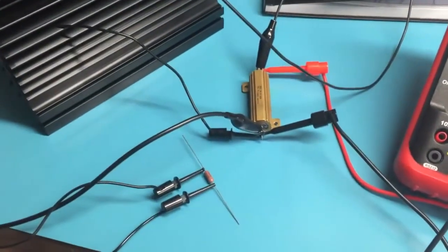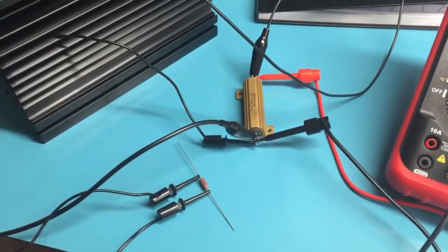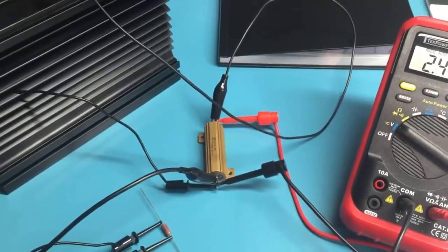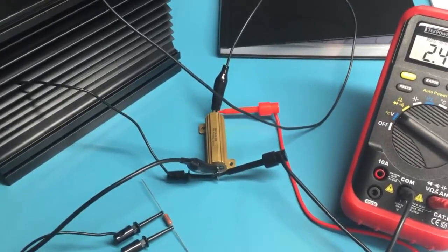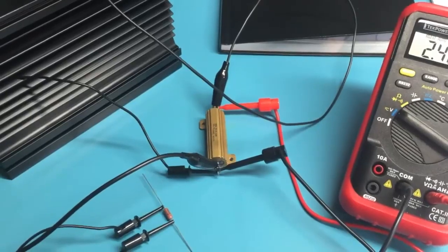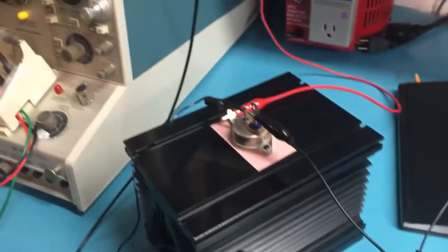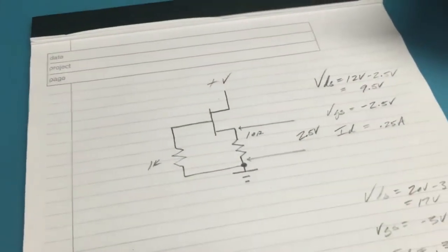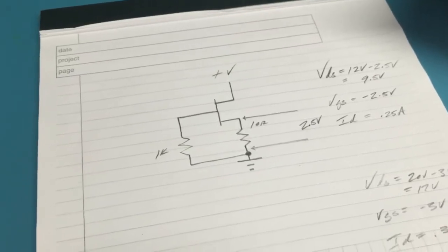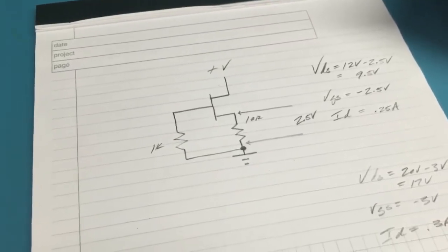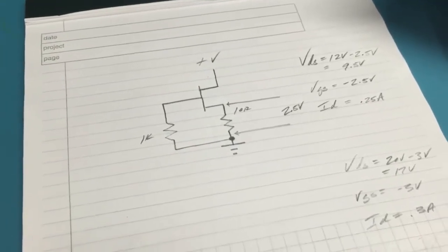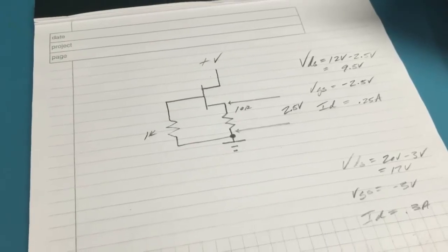You can see we've got a 1 k ohm quarter watt resistor there, and a 10 ohm 50 watt power resistor. It's not on a heatsink right now, so it's derated to 5 or 10 watts that way. And there's our SIT, and it's wired into this contraption like so. Our bench power supply is attached to the drain, and the source is attached to ground through that 10 ohm resistor, and the gate is attached to ground through that 1 k ohm resistor.